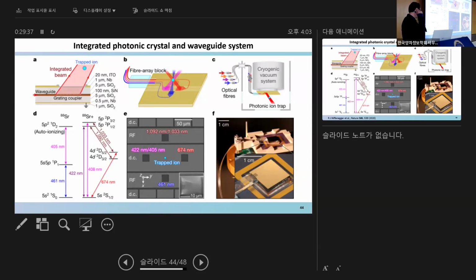Several years ago, people talked about building chips with semiconducting materials, but there are too many issues. Still, some people are pursuing that direction, but a lot of them nowadays are working on just glass. You have a glass, and then you do gold coating on the top, and try to use UV-handleable materials, something with less charging issue. So people are going away from semiconducting materials now.